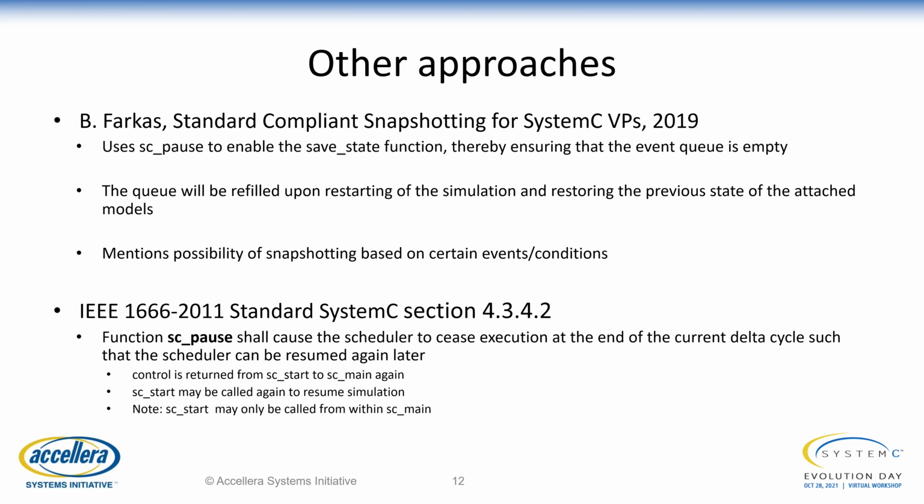I can later resume the simulation using sc_start. So that is what I'm going to use. There's, however, one note: sc_start can only be called from within sc_main. So there are some situations where it might not work out completely, but we'll come to that later.